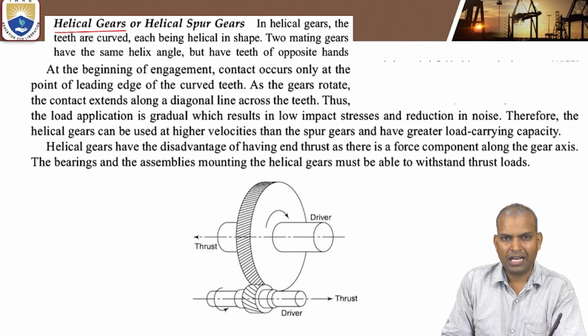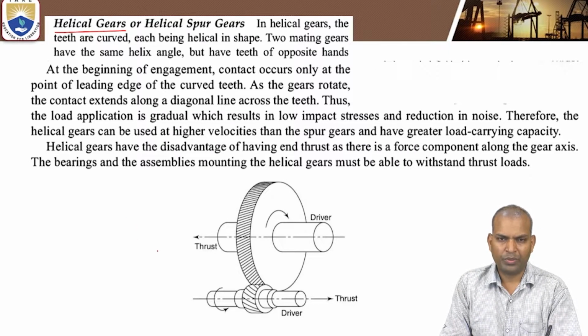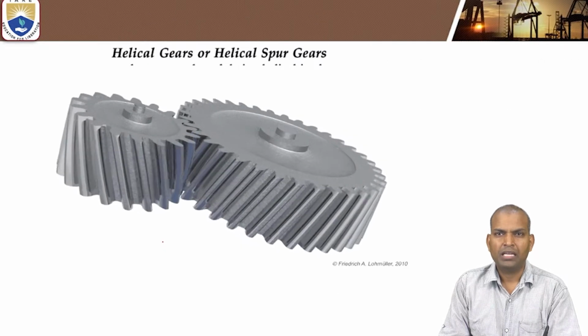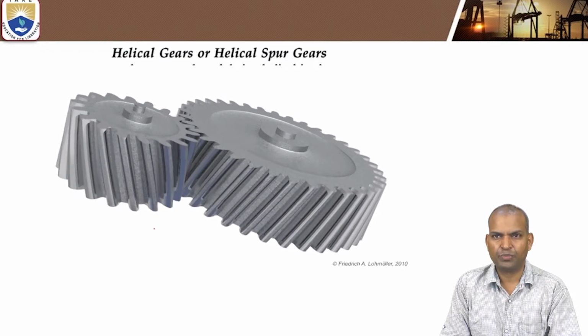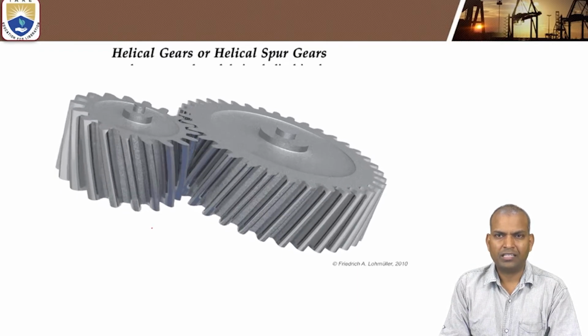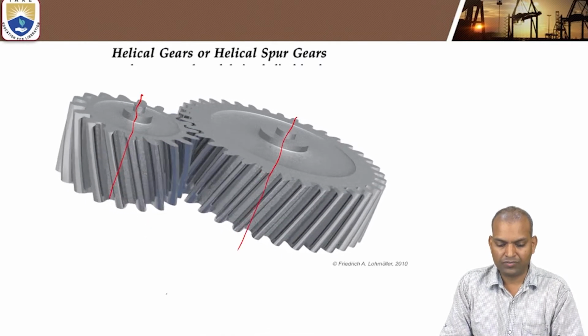These helical gears, in comparison to the spur gears, can transmit more power with less noise, and can also be used at high speeds. The contact between the two helical gears looks like this and transmits motion. But one thing is that both the shafts are parallel shafts.